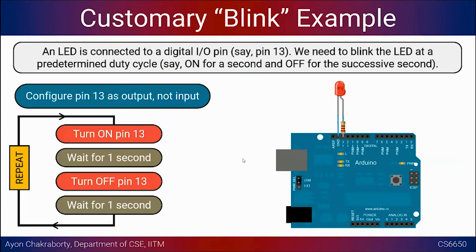In the same way, we don't have a console that is attached to this Arduino device. The only input output pins are the medium of communication to the device. So if you want the code to do something that is visible from the outside world, a very simple thing we can do is turn on and turn off an LED from the program. Pin 13 is one of the pins in the board that is marked here. So we attach an LED to this digital input output pin 13, for example here.